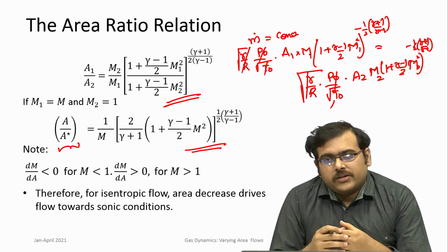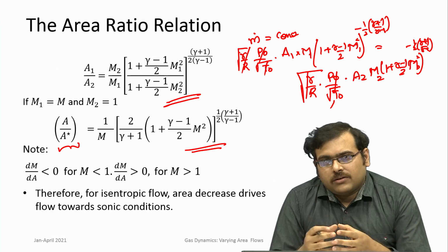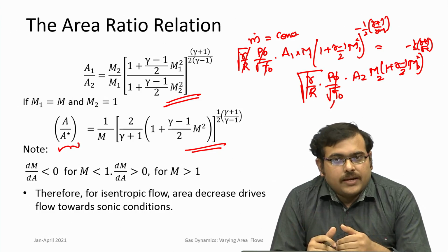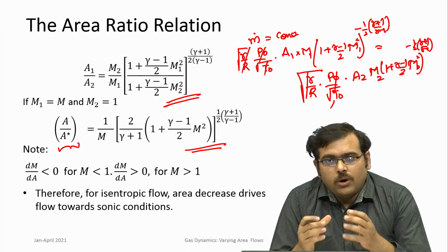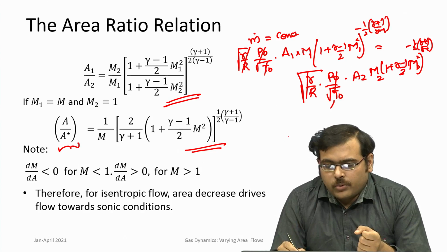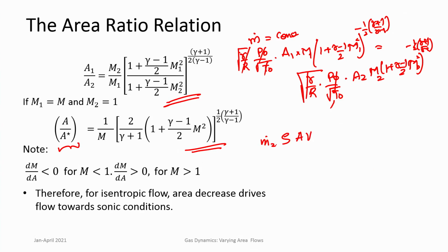If you know the stagnation pressure and temperature, or what are known as reservoir conditions, then you can use another expression, or you can always go back, calculate the basic variables rho, A, V, and mass flow rate can be calculated. M dot is equal to rho A V.